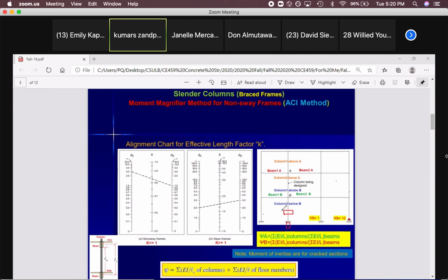So b is parallel to the bending axis, h is perpendicular to the bending axis. So b h cubed divided by 12. If you have a column like this, again b is here, parallel to the bending axis, h perpendicular, the same. Just try to find the correct names, b and h, then the same equation, b h cubed divided by 12. Bending axis, don't forget. This is very important.